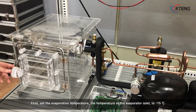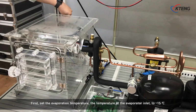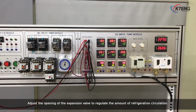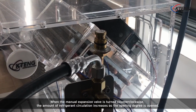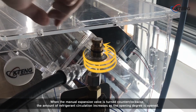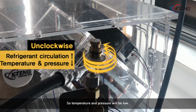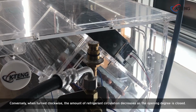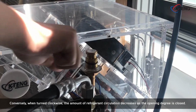First, set the evaporation temperature, the temperature at the evaporator inlet, to -15 degrees Celsius. Adjust the opening of the expansion valve to regulate the amount of refrigerant circulation. When the manual expansion valve is turned counterclockwise, the amount of refrigerant circulation increases as the opening degree is opened. So, temperature and pressure will be low. Conversely, when turned clockwise, the amount of refrigerant circulation decreases as the opening degree is closed.